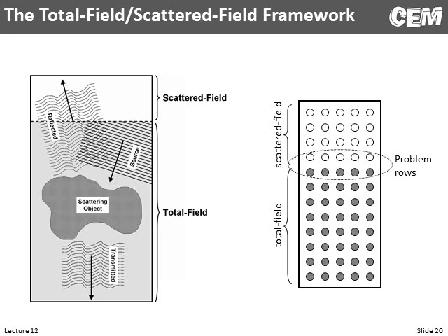So how do we implement this? It starts off by just declaring it. Now what we have to do is make sure that our finite difference equations are consistent with that. So let's go ahead and look at our grid. We have a 2D grid, and each of these little circles is representing one point on the grid. And we know that we have finite difference equations. We have a finite difference equation associated with each point that couples each point to its neighbors.